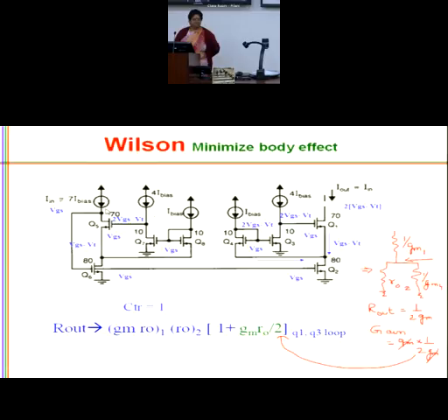Its only purpose is this. But this is critical. Why? Because this is giving you gain boosting. Because here, a variation here, because of say node fluctuating, because of amplification process, this node will also fluctuate. So this node will also fluctuate. So a minus gain times fluctuation appears here, which causes a negative feedback.